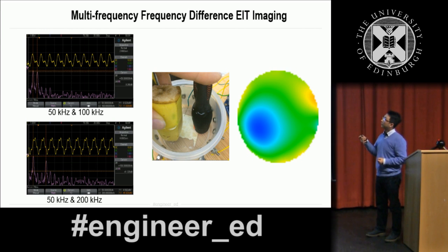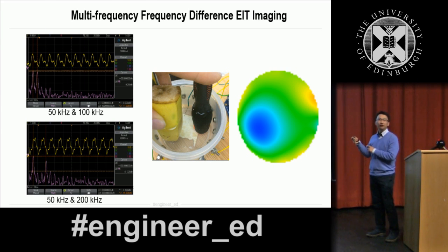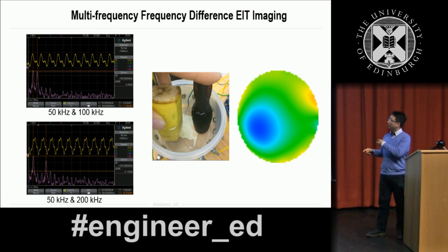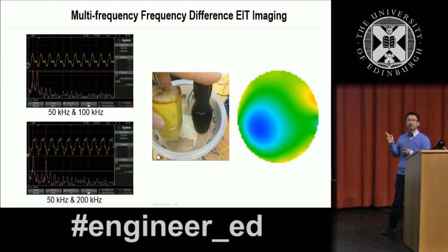So if we use a frequency difference like this one, it's a banana or a screwdriver. We don't need to measure the water only, we just use different frequencies to get an image. The screwdriver is non-conductive and has no reaction with frequency, but the banana has cells, membrane. It has a capacitance component there. It has a reaction with frequency. That's the knowledge of first year electrical engineering.